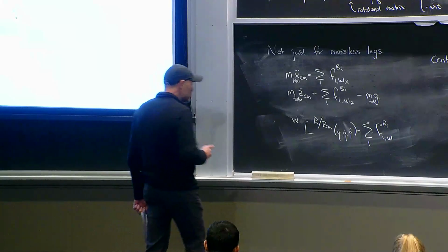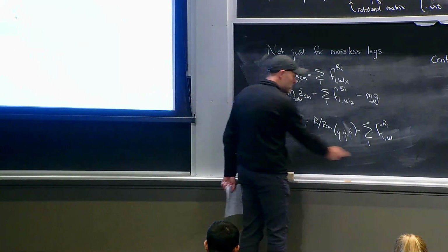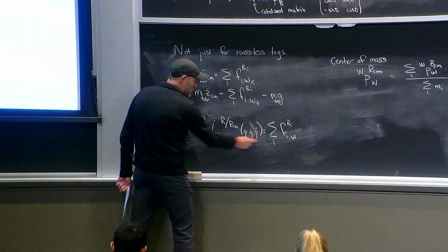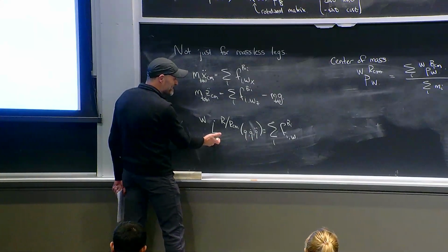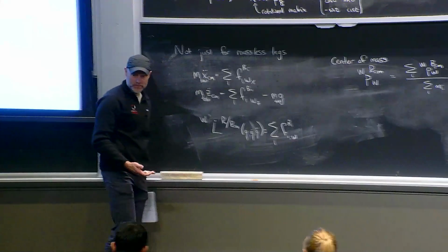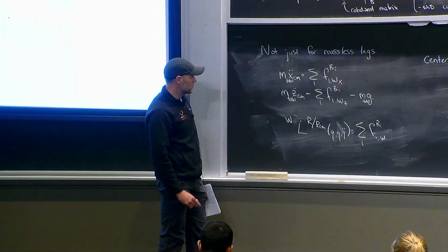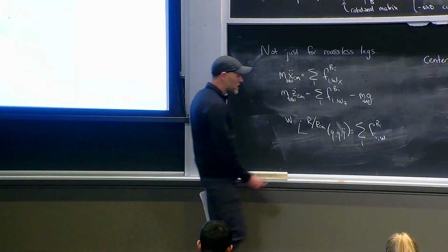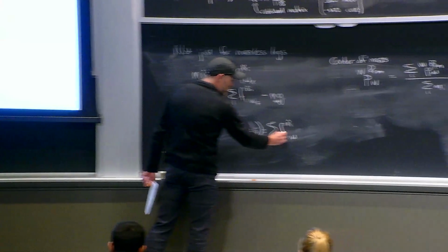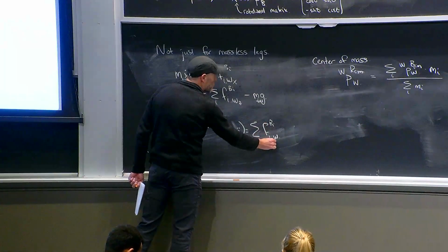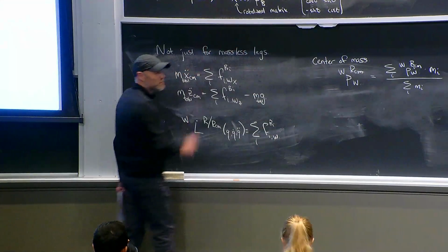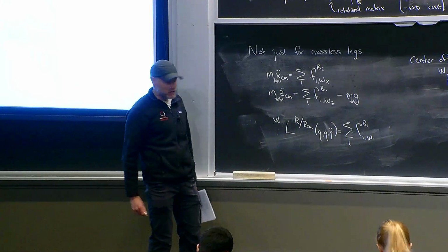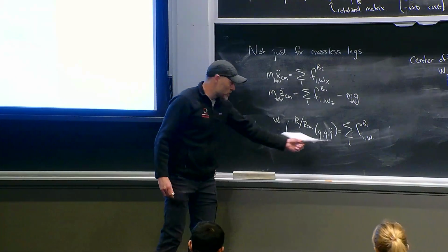And it turns out that computing the left-hand side is a complicated set of equations, but the dynamics in the center of mass frame are super simple. There's some work being done by the notation here. When I say that I've got the spatial force in the world frame, it has that cross product sitting inside it in order to write the spatial force properly. But the generalization is like this.